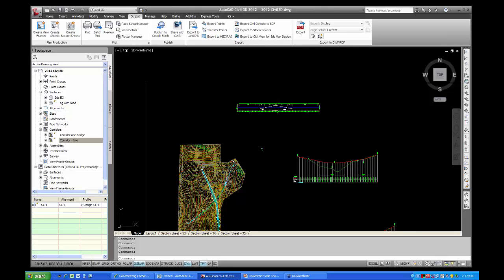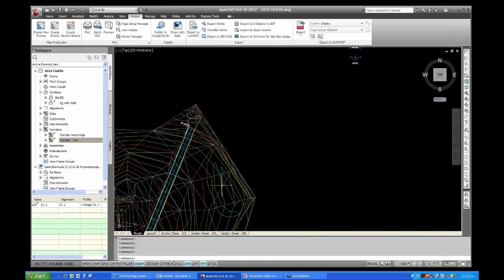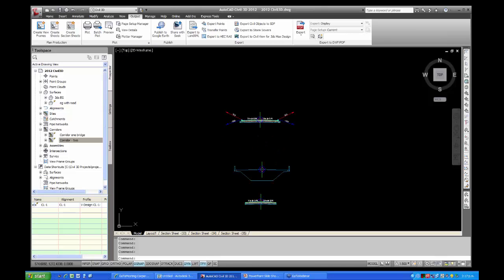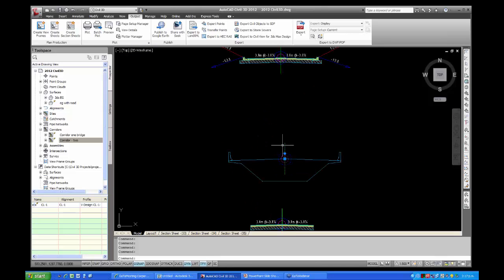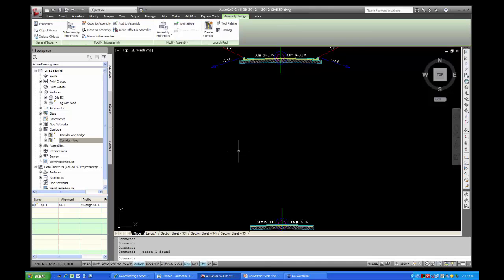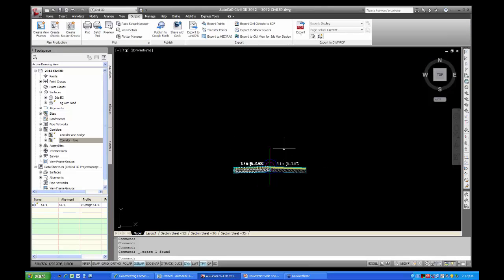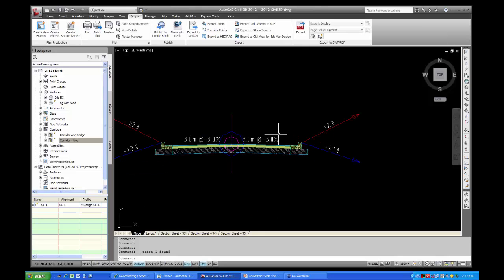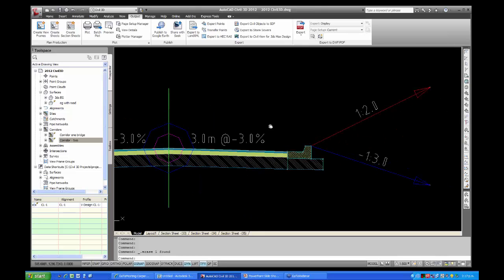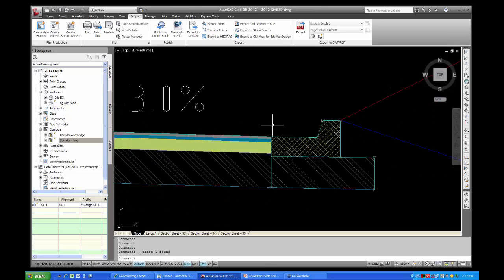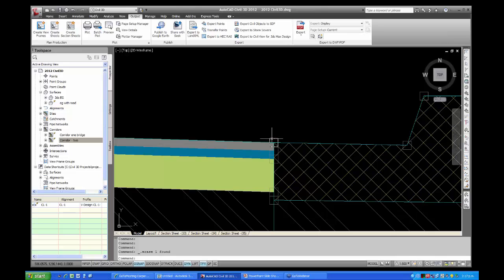Now, there's a whole bunch of feature lines on these corridors. But what I've done is I've come through in here. Actually, that one doesn't exist, so we don't need it anymore. The cross-section for my road is up here, and down below it is the cross-section. I've just put a basic cross-section for the bridge because that's all you need. In here where I've wanted particular feature lines output, I've come in and put what's known as a marked point. You can see if I zoom in on this thing, only that little square highlights.